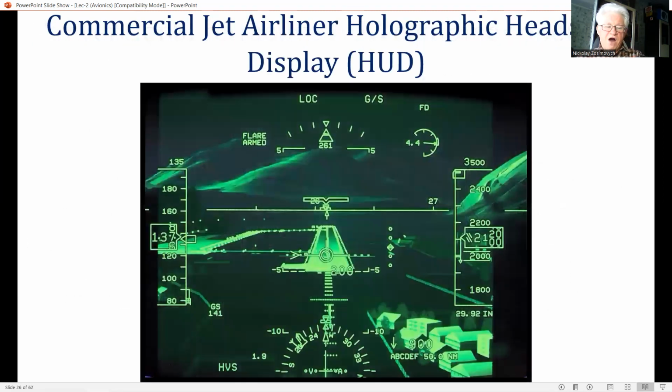The need for a wide FOV when maneuvering at night at low level can be seen in this figure. The wider azimuth FOV is essential for the pilot to see into the turn. The analogy has been made of trying to drive a car around Hyde Park Corner with a shuttered or blacked-out windscreen, with your vision restricted to a hole punched through the window.